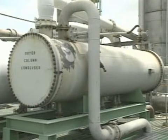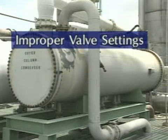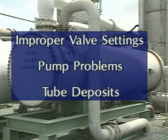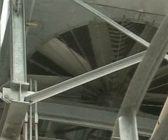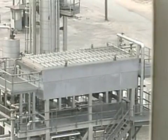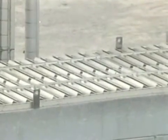Some common conditions that can reduce the cooling water flow through a shell and tube condenser are improper valve settings, problems with the cooling water pump, and deposits in the condenser tubes caused by impurities in the cooling water. In a fin fan condenser, the cooling medium is air. One of the main problems that can reduce the flow of air through a fin fan condenser is a problem with the fans. Also, some fin fan condensers have louvers to help control airflow. In these condensers, airflow can be reduced if the louvers stick in the wrong position.